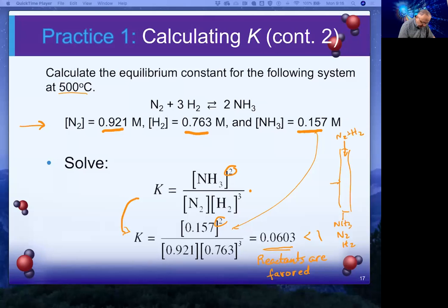Now, ammonia actually condenses. I think at minus 15, minus 20 degrees centigrade, it will condense. So what they do is they pass it through a cooler. And so the ammonia condenses as a liquid, and it can be separated from the gas just by gravity. Then the gas is recycled with a stream of nitrogen and hydrogen that is coming in again, and it passes again through the column. That's the way that ammonia can be produced. And the hydrogen is not wasted, because this will reach equilibrium as it goes through the column. There's a catalyst that makes it very fast.